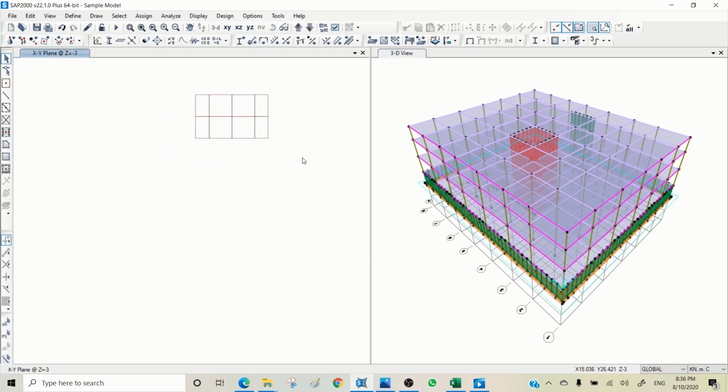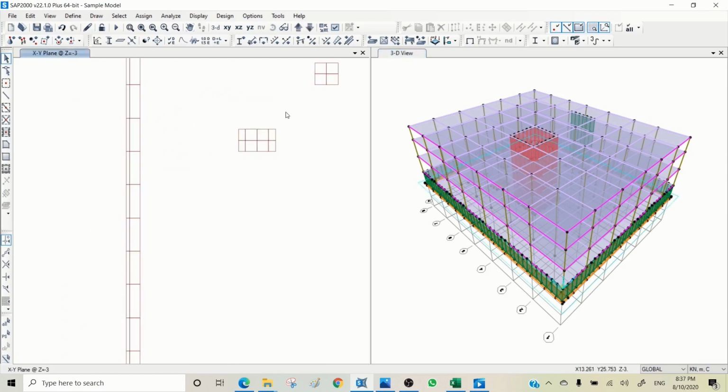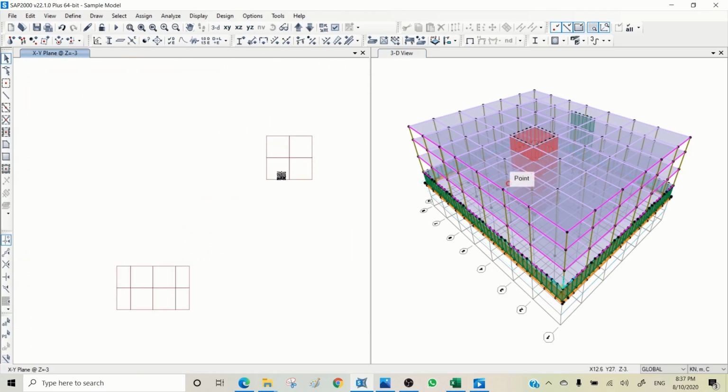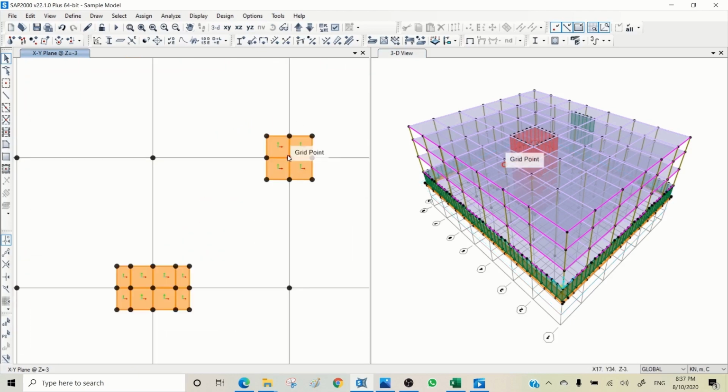The other pile for this column, I want to make the pile cap smaller because I have just one pile below. So say 600 pile, half of a diameter each side. We have more for size of pile cap, so 300 each side is 1.2 in total. So this is 2 meters, so to 1.2 is 800 millimeters, so that would be again 400 millimeter move.